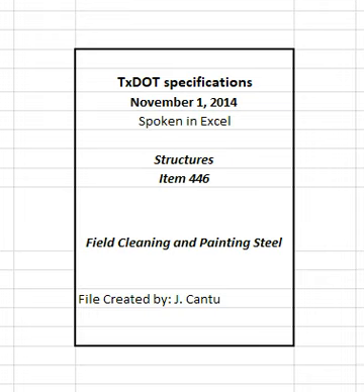2.2 Paint inside tub girders and closed boxes. In accordance with Item 441, Steel structures. 2.3 Paint over galvanizing. In accordance with Item 445, Galvanizing. 2.4 Special protection system. Provide the type of paint system shown on the plans or in special provisions to this item. Special protection system paints must have completed NPEP structural steel coatings, SSC, testing regimen as a complete system, with full data available through NPEP unless specified otherwise.